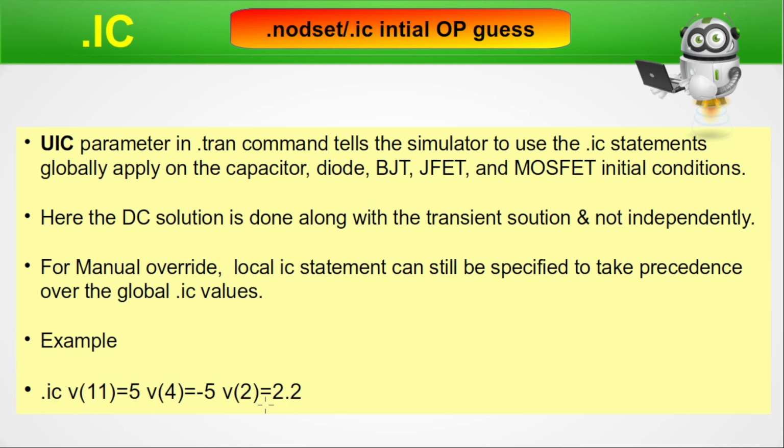These are very crucial things of a SPICE. Even if you use an industrial simulator, the .NODESET and the .IC are very much important, because these will decide how the simulator is kickstarting the simulation. If the kickstart is wrong, then the entire simulation will go wrong. So these are two very crucial points. You have to be very careful about them, and you have to use them cautiously, judiciously, as per the need.